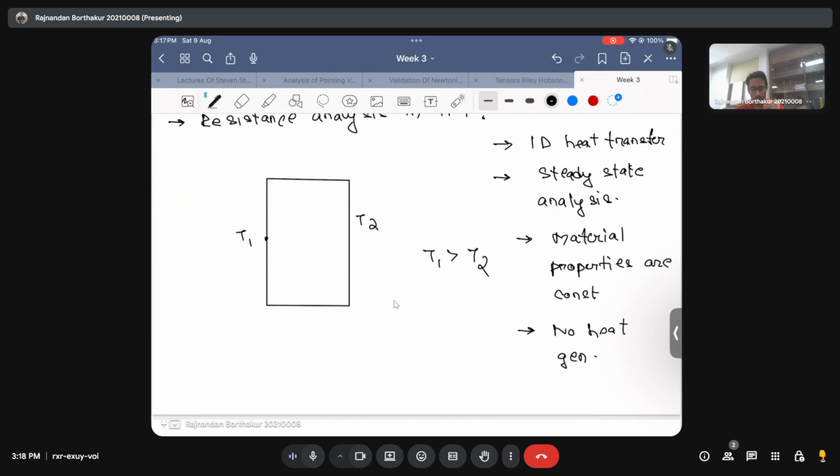In that context, you know that your heat flux is going to be constant, or you know that your temperature profile T as a function of x, where the plus x direction is from the left to the right, which is what we conventionally use. And you can tell that the temperature profile, which will now be just a function of x, is going to be linear.